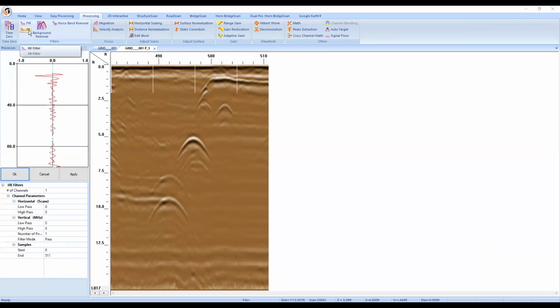You will see a very similar result no matter which one you use, but there is a slight risk of a phase shift using the FIR filter. Phase shift meaning the amplitude might shift up or down by a few samples, which can affect the depth accuracy. Not by any really catastrophic amount. We're talking on the order of a 64th of an inch, but it's still a possibility.